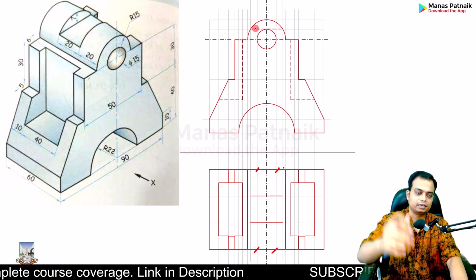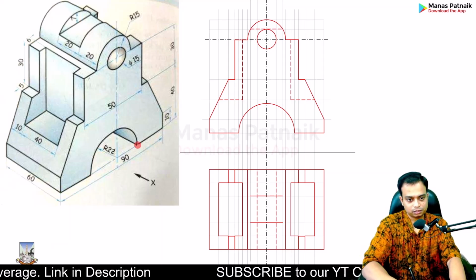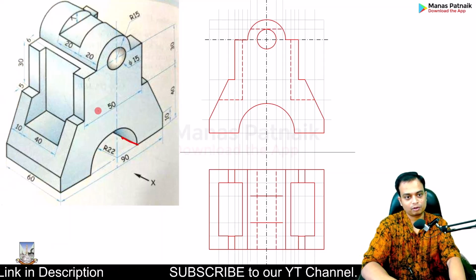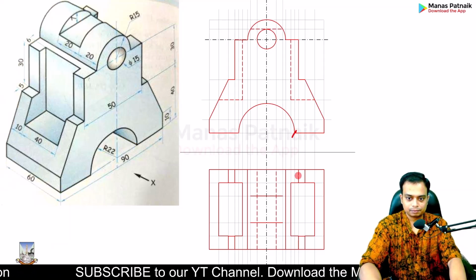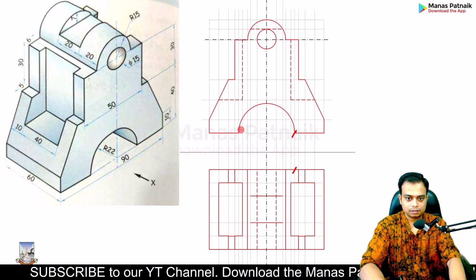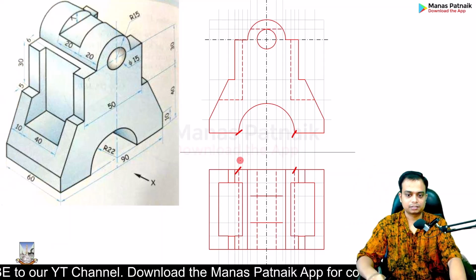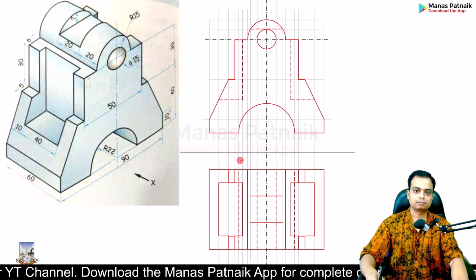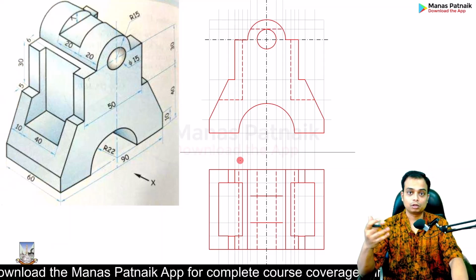Circular profile. Drill throughout. This is how it would look. And this portion, this edge is not going to be visible from the top. And therefore, where does it start? Here, here, here, and dashed lines for hidden features. Done. It is done. Okay, make sure that you put all the dimensions like this.